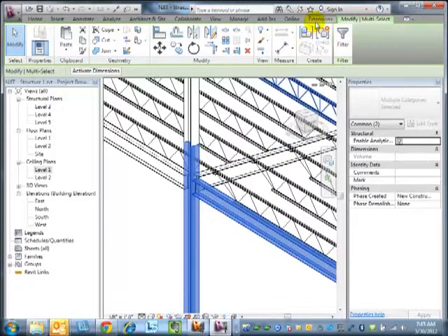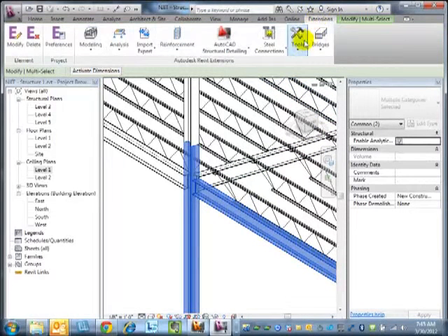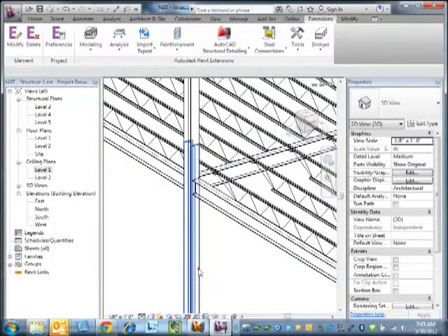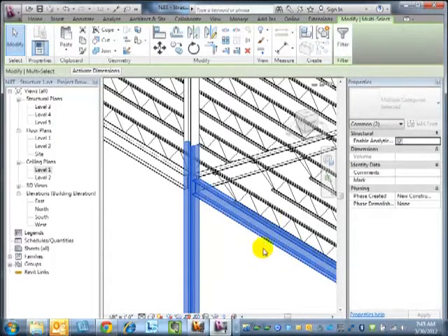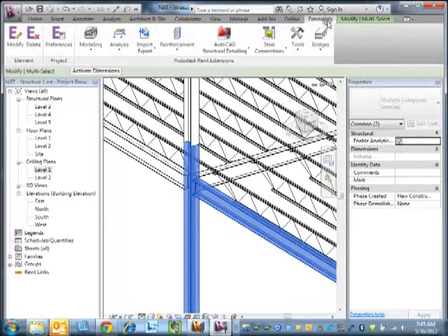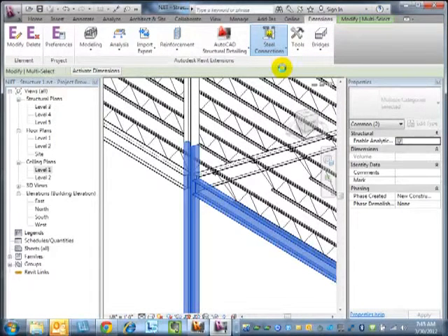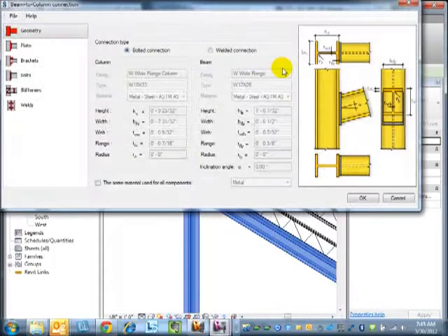There are extensions to Revit Structure that will help you clean up those things, including a steel connection sort of extension. So if that's not looking exactly like what you have in mind, we tend not to do this to all of our different details or all our different connections, but when you want to go through and start detailing out one, you can do something like a beam to column connection. It loads in, it's a little piece of Autodesk structural detailing to make this happen.